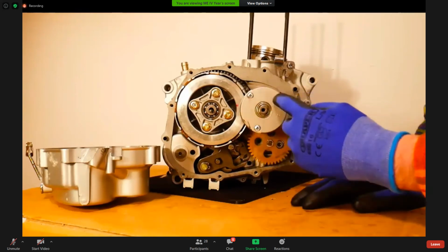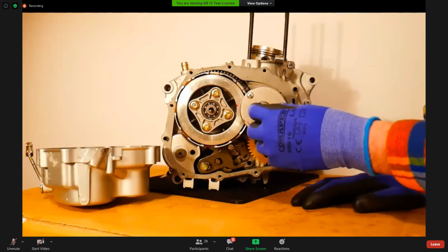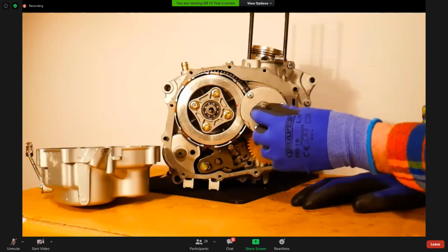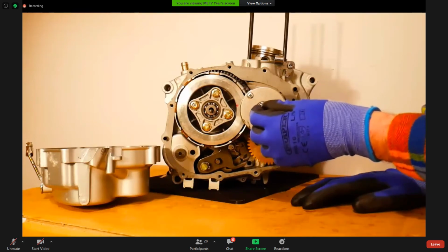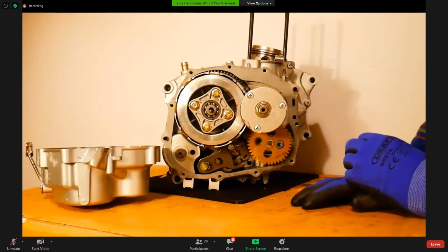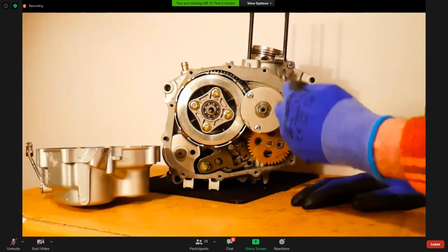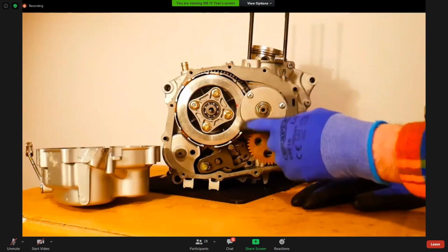Any heavy components in the oil will remain as a residue around the rim of the centrifugal oil filter. It will obviously fill up with oil, and the oil will build up until it builds up in the middle of the filter. In the middle, the oil is not spinning at high speeds and it's not experiencing the centrifugal force.